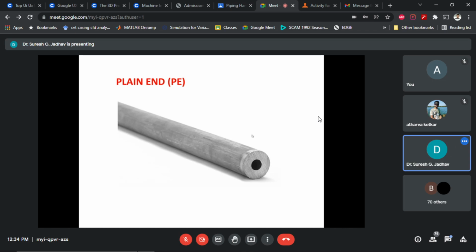For instance, if you consider 3/4 inch with a schedule, that is a wall thickness, ASTM A312 TP316H, it is threaded on one end and plain on the other end. In contrast, if you consider 3/4 inch with schedule 40S, the pipe has threads on both ends.